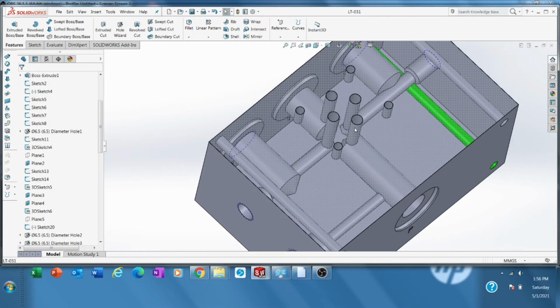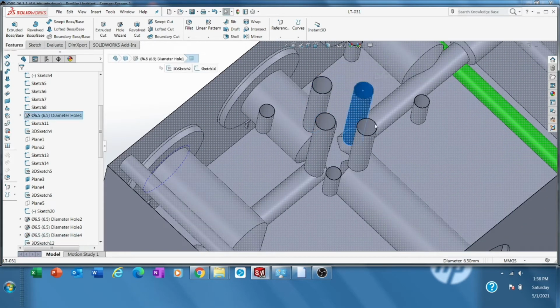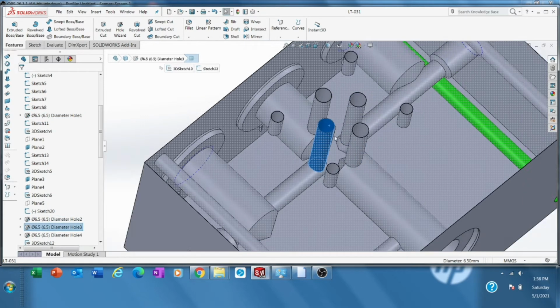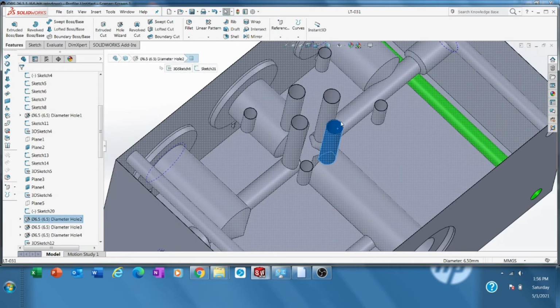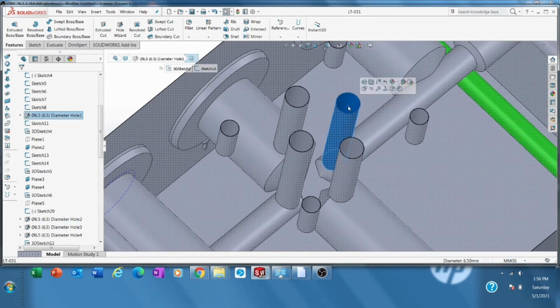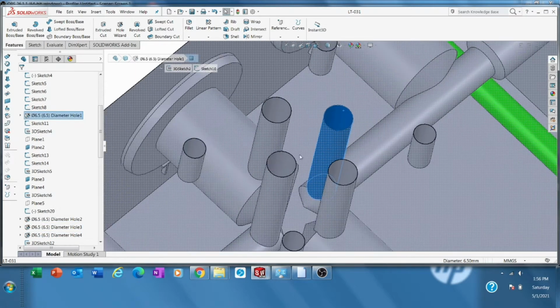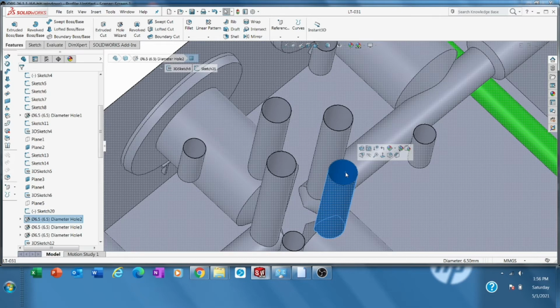And then these 4 holes are what we call the holes for P pump or pressure section, for A and B, and for tank. And the dimension of this, the distance and diameter, is ISO standard for all models, all manufacturers.